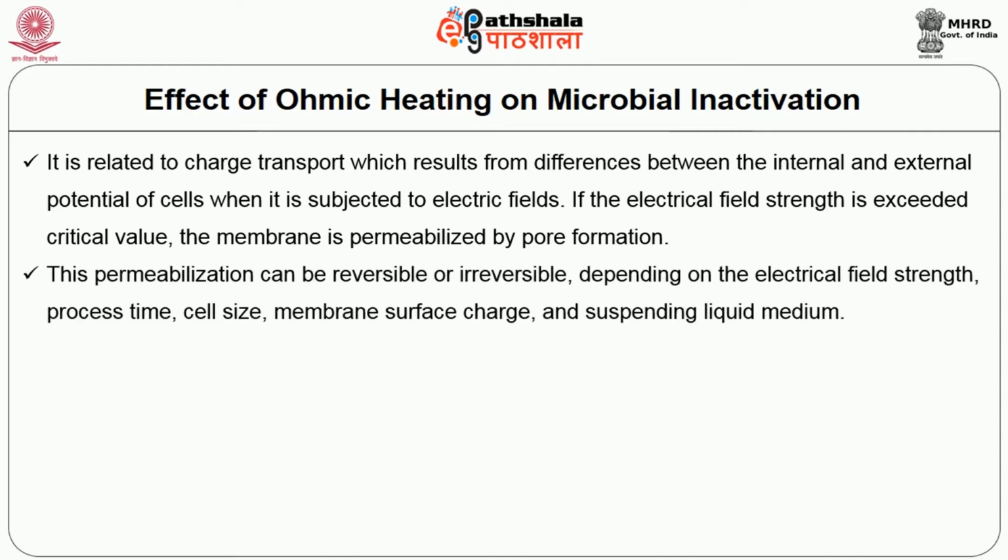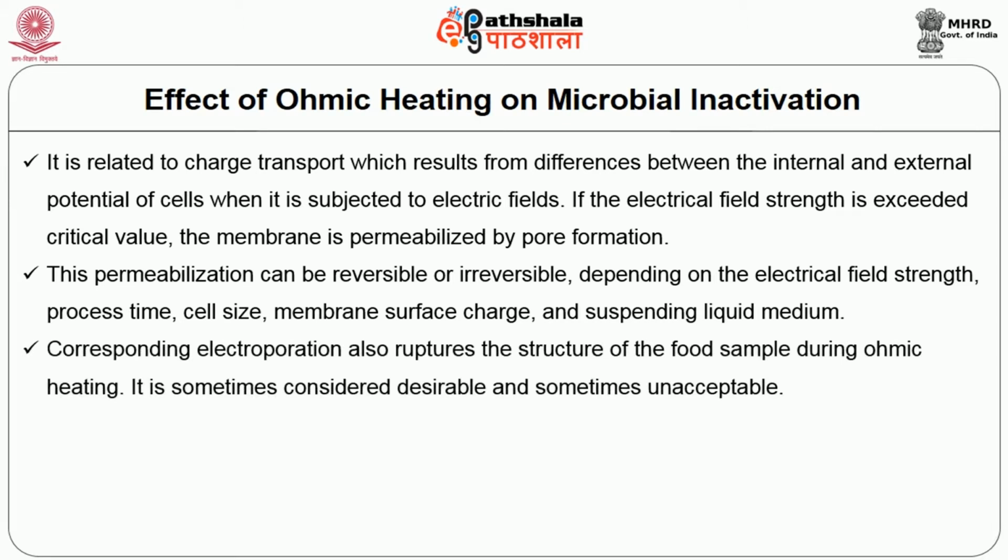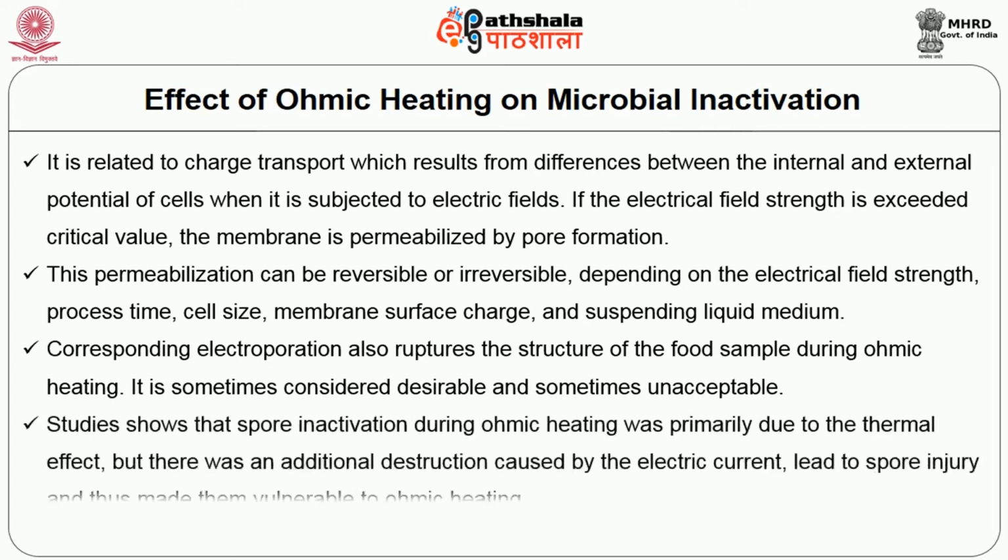This permeabilization can be reversible or irreversible depending upon the electrical field strength, process time, cell size, membrane surface charge and suspending liquid medium. Correspondingly, electroporation also ruptures the structure of the food sample during ohmic heating. It is sometimes considered desirable and sometimes unacceptable.